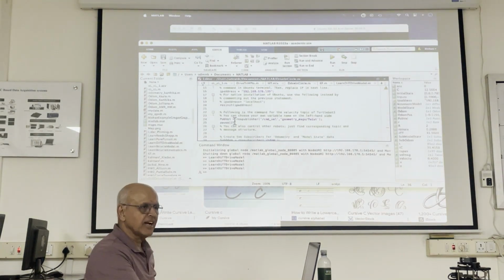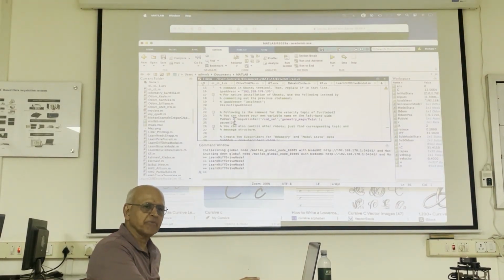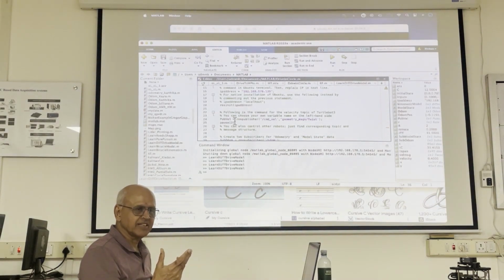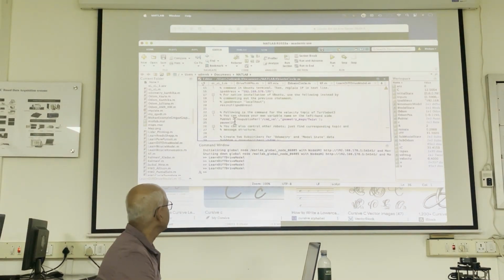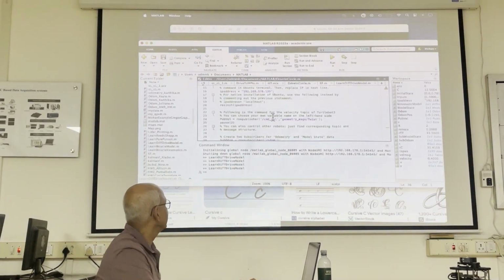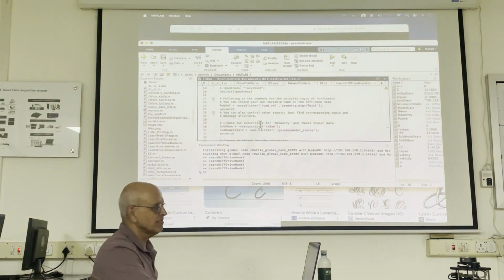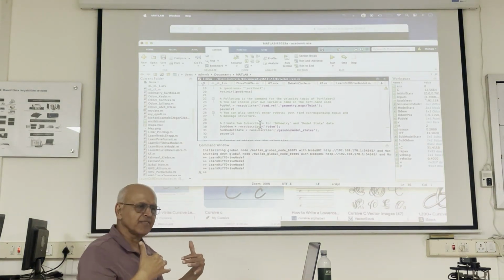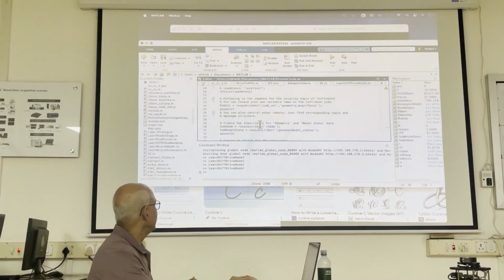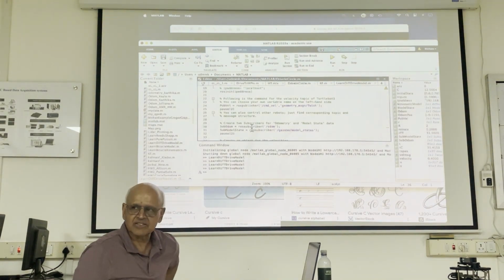Then after that, you come to the publishing subscription block, right? Because you can't run a program in MATLAB that talks to Gazebo and ROS if you don't have some topics that you're interested in. So there are 2 kinds. There is the command vel, so that's how you're going to give commands to the robot. And then there is the odom, where you get position information from Gazebo.